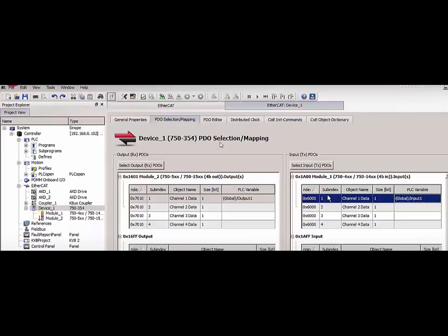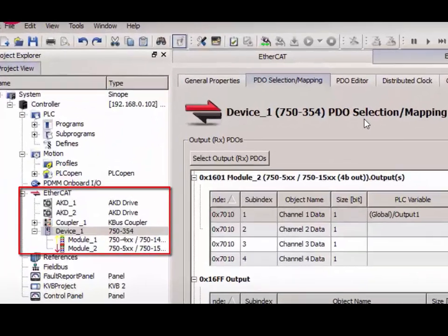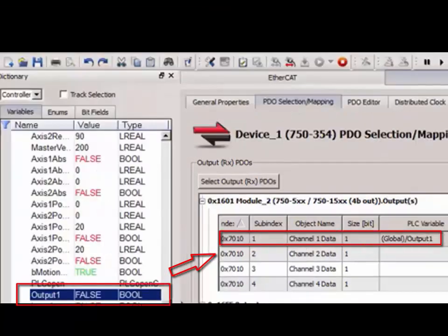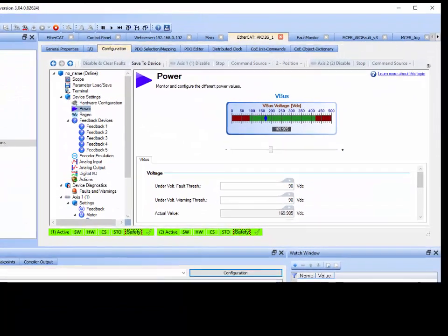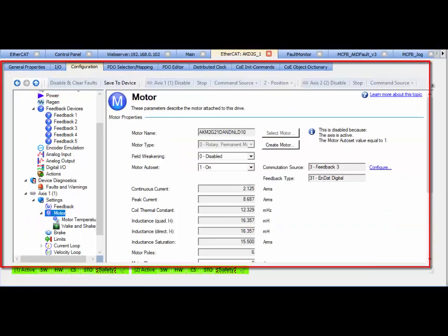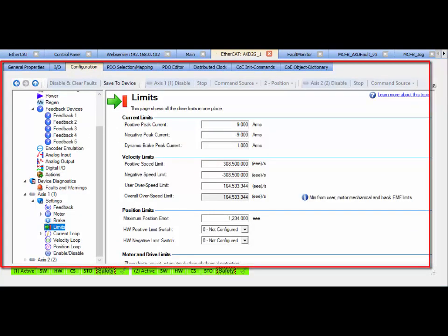KAS incorporates the industry standard EtherCAT network to tie the KAS controller to Kollmorgen servo drives, Kollmorgen AKT remote I/O, and also third-party devices such as an inverter drive. Through features such as offline setup, scanning to find all devices on the network, and drag and drop to connect device parameters to program variables, the integration process is simplified. The Kollmorgen Workbench environment is integrated into the IDE for setting up servo drives, making the IDE a one-stop place to set up both controller and drives.